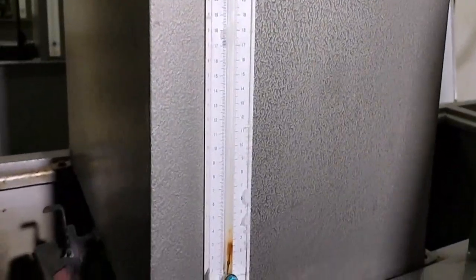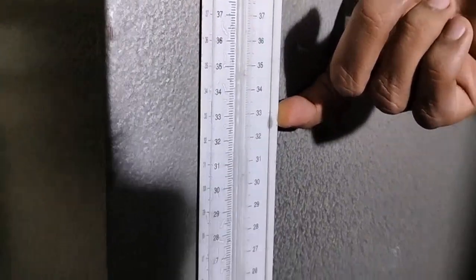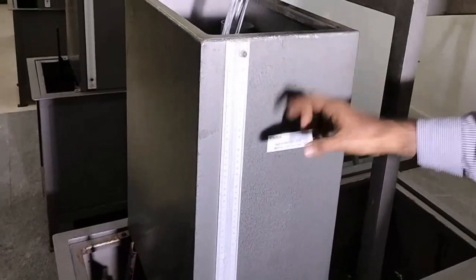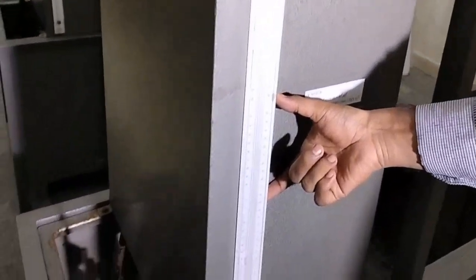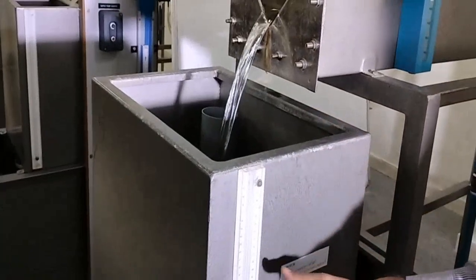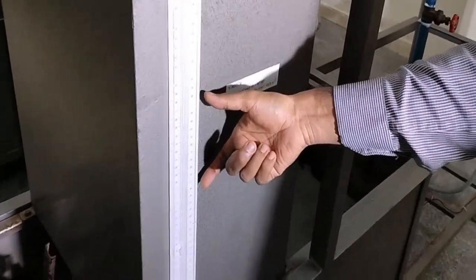For the 10 centimeter height, how much time is taken should be found out using the stopwatch. For example, 36 to 42 centimeter. For 10 centimeter height, how much water is collected will be noted from the stopwatch. The procedure is the same. For the known height of water level rise, how much time is taken should be taken from the stopwatch. In all the experiments, we will consider for 10 centimeter height how much time is taken, measured by the stopwatch.